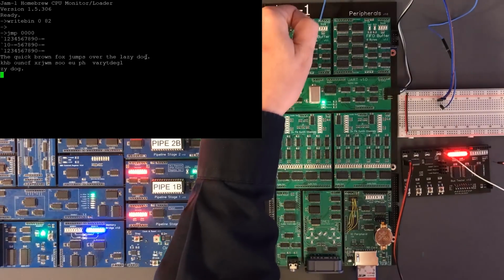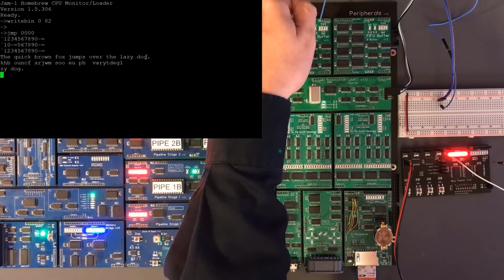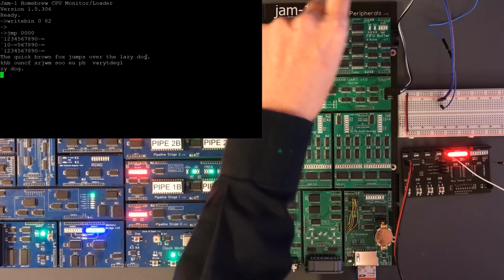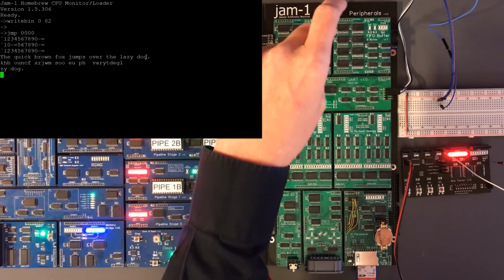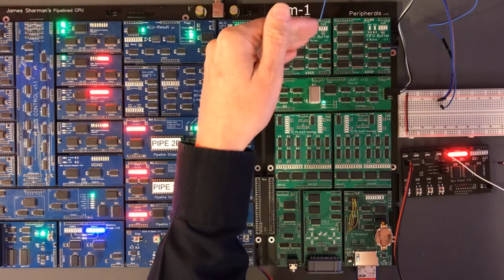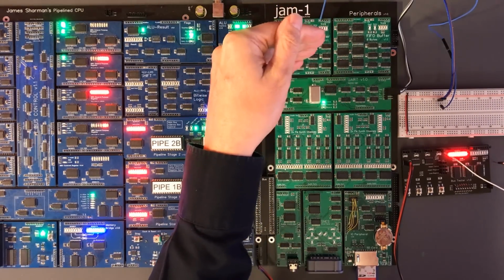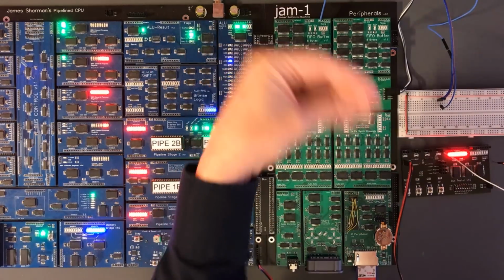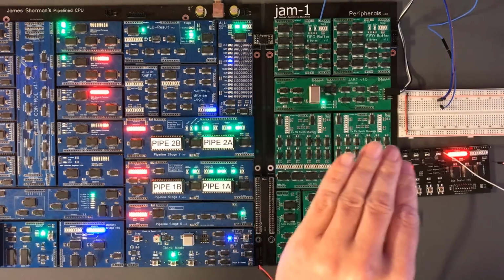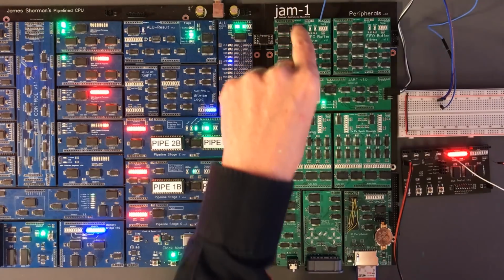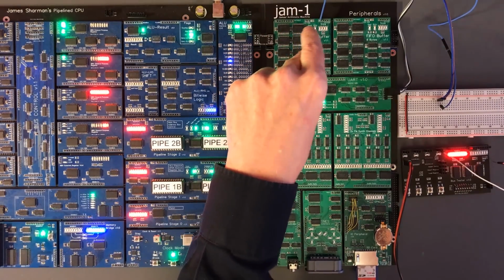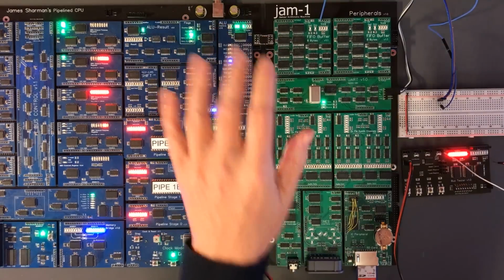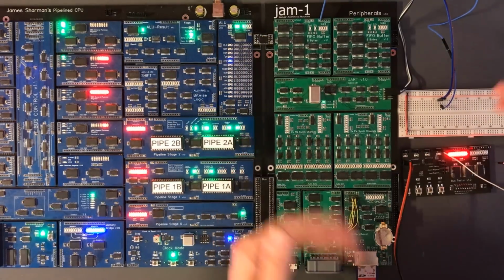And the reason why this has happened is because whilst the clear to send line has been sent high, meaning it's not okay to send, the moment this FIFO is full, the sending device is probably already sending a character. So that one's getting messed up, and possibly more because we've got no idea how much latency there is. So what we need is to monitor the amount of data in the buffer and bring that line high when we're approaching full but not entirely full. So we're going to need to build a circuit.